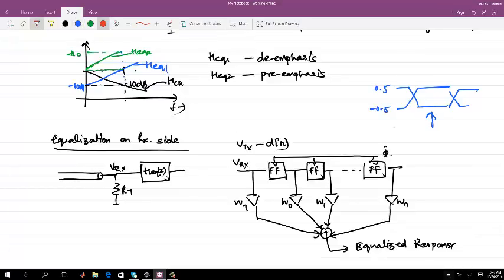In case of the receiver, what you have is not that clean. It is basically more of a junk. It can be like all this is there. It can be anywhere, but I still am able to sample here somehow. But the amplitude variation can be a lot. That's the only difference. I need to just open the eye and sample the bit. Now what is the difference you see? What are the challenges which you will face, which you didn't face when you implemented on the transmitter side?